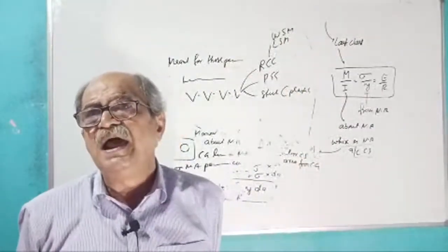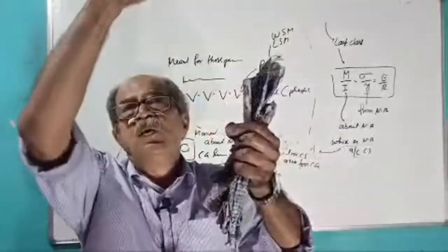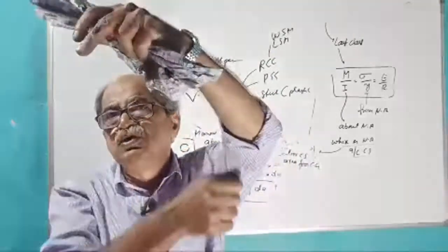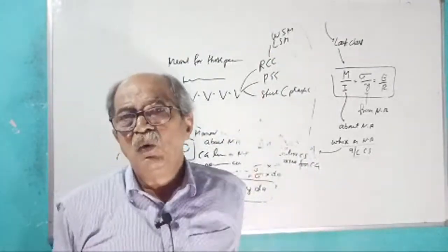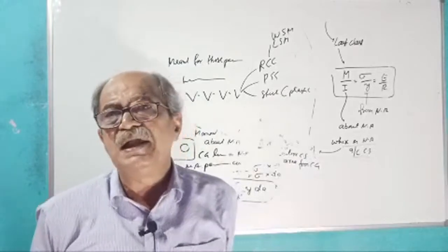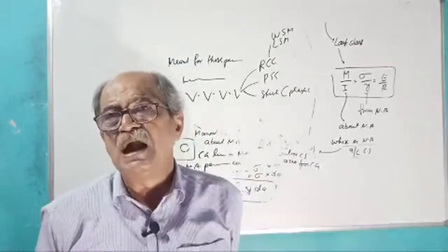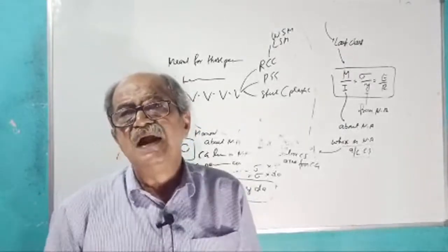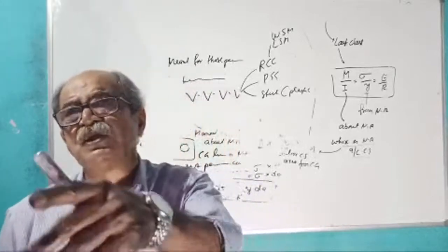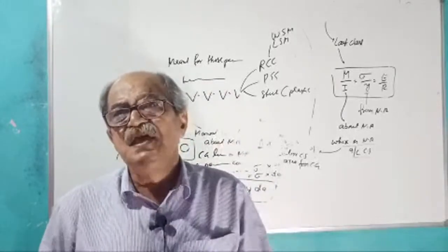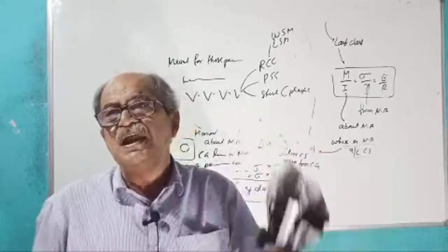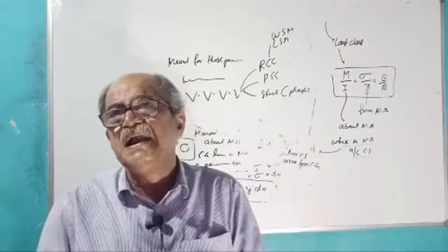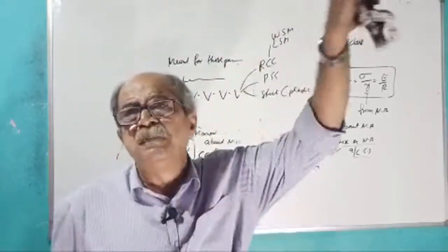It is called the equal area axis. Then the lever arm: from the CG, Y1 bar and Y2 bar, the total lever arm is Y1 bar plus Y2 bar. Therefore MP equals Fy into Zp, where Zp equals A by 2 into Y1 bar plus Y2 bar. That is the sum of moments of the compression and tension areas about the neutral axis. Clear? These basic concepts are used in RCC, working stress method, limit state method, steel structure plastic analysis, and also in prestressed concrete.